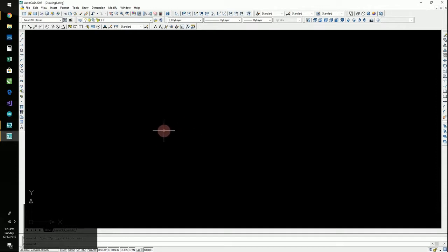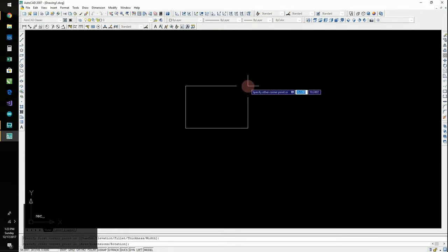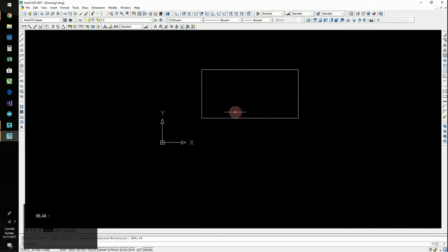So, all right, let's get part sheets ready. We basically want to work on, let's say, a 4x8 sheet of material, whatever it is. Plywood is generally what I use. So I'm going to go ahead and create a rectangle. The way I do that is I hit REC on my keyboard, click, and then as long as I'm in ortho, which I should have set up, I can just type in my sheet material is 96 wide, comma, 48 tall, and then enter. And that's going to make this the base material that I'm going to put my parts on.